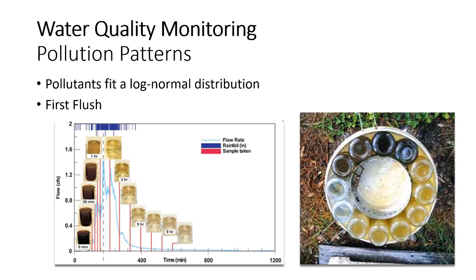in terms of characterizing urban watersheds. The other thing to know is that in general, if you're taking a bunch of samples of pollutants, just any of them in an urban watershed, they're typically going to fit a log normal distribution. So you'll have a lot of, let's see, maybe this will help. If you think about sampling over this storm event and then way out, if you keep going out, you're going to have a lot more samples that look like this than look like this, right? Because you have a lot of time in between the next storm event. But then you have that storm event again here, and you'll have this kind of samples again. So you're going to have a lot of samples that have lower concentrations, but then a few samples that have really high concentrations, so that's not going to be a normally distributed data set. Okay, just something that's important to know.